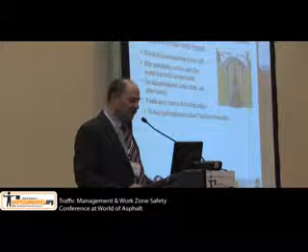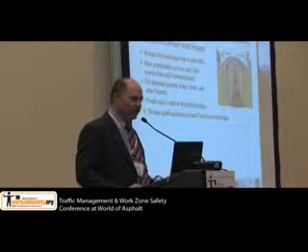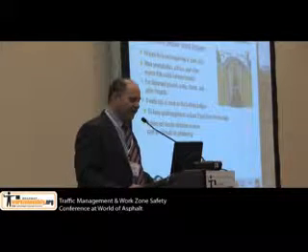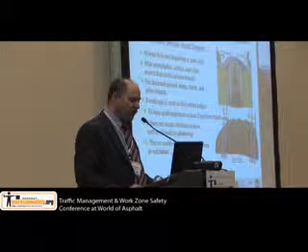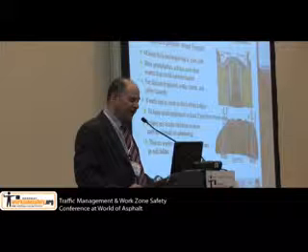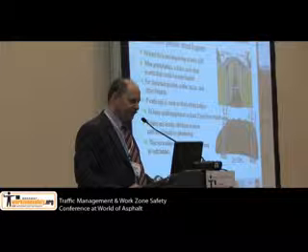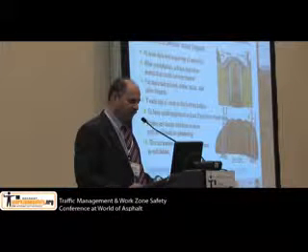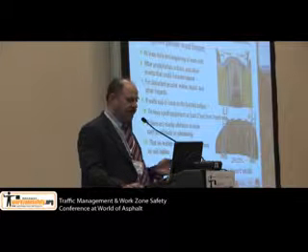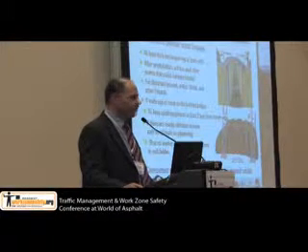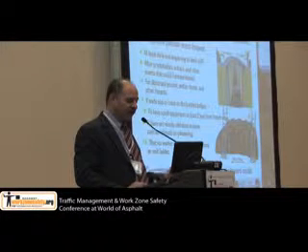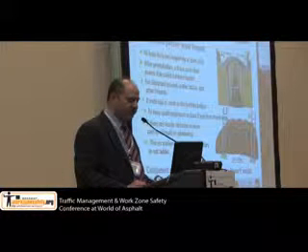They keep equipment and the spoils pile at least 2 feet away from the trench edge, check for any vibration sources, and make sure that no worker is more than 25 feet from an exit ladder. And as I mentioned, they should stop the work if a hazard exists. So that's really one of the major hazards that we wanted to address.